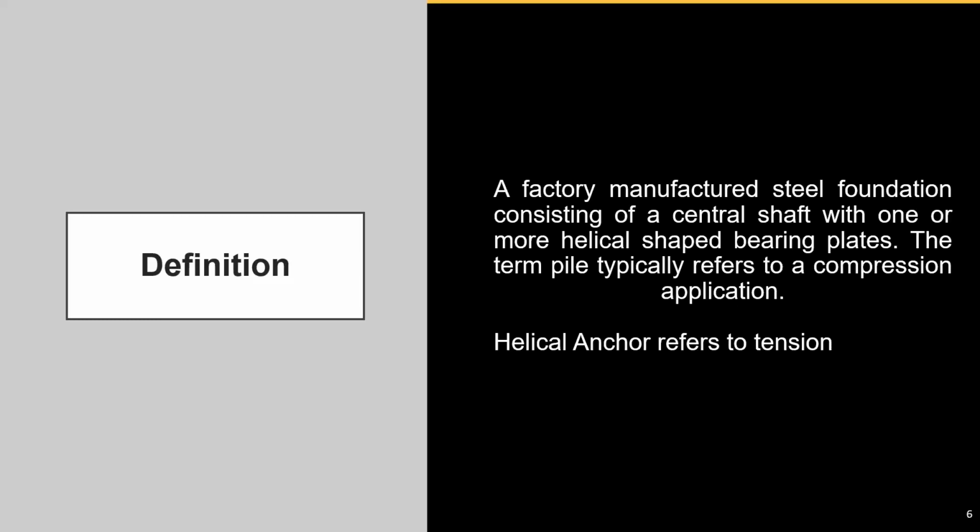Whereas for these small diameter helical piles, you will see what the capacity correlation factor KT is. Again, a helical pile is just a steel central shaft that has these helical plates welded to it. The most common type of small diameter shaft is the 2-7/8 inch outside diameter shaft, the 3.5 and the 4.5. For the square shaft, these are solid ones, the 1.5 and the 1.75 inch. These are the most common helical pile anchors out there.